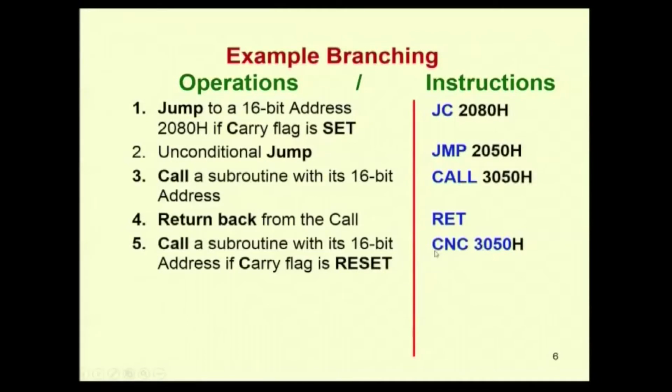That is call no carry: C means call, N means no, C means carry, followed by 3050H. Then again a conditional return instruction, return if zero flag is set. R corresponds to return and Z corresponds to the zero flag.